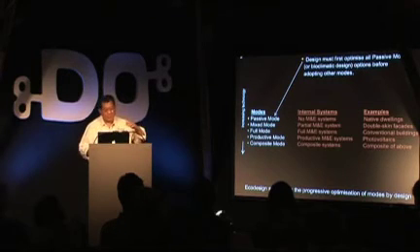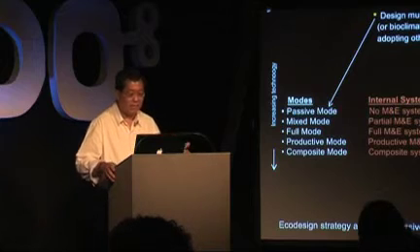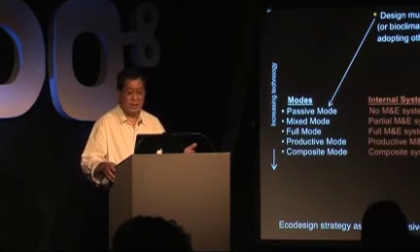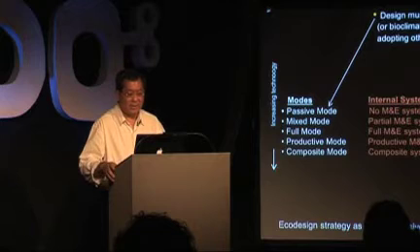And so I conclude that there are basic ways of creating conditions of comfort. I call them passive mode, mixed mode, full mode, productive mode, and composite mode. Passive mode means improve comfort conditions without any mechanical electrical systems. If you look at the native dwellings for any locality, because in those days they didn't have electricity, they didn't have mechanical electrical systems, native dwellings were built to improve comfort conditions without any mechanical electrical systems.